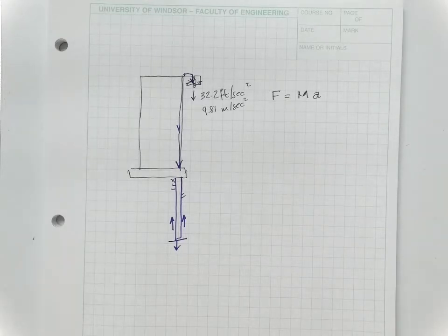Hopefully, as long as the steel mill is on my site, it may work. If I have to transport it on the highway system, it's not going to work. But I can cast a beam out of reinforced concrete 250 feet long. You do it in relatively short order. And so one of the advantages is I can have long continuous members.